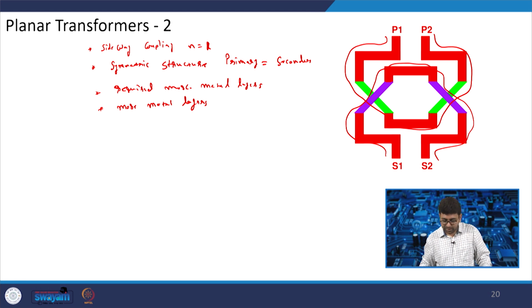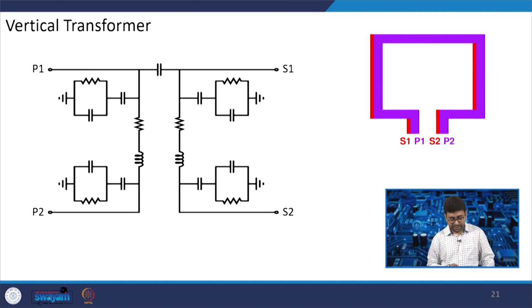This is about the transformer, where you can also draw it like this. If you want to model the transformer, it will be the same as an inductor. You can also use a different metal layer. In this, one metal is used, the top metal, and there is one metal below. But in the top metal there is air, and in the bottom metal there is a dielectric. So a mismatch is possible, but this kind of transformer is also available, and you can design it on chip.